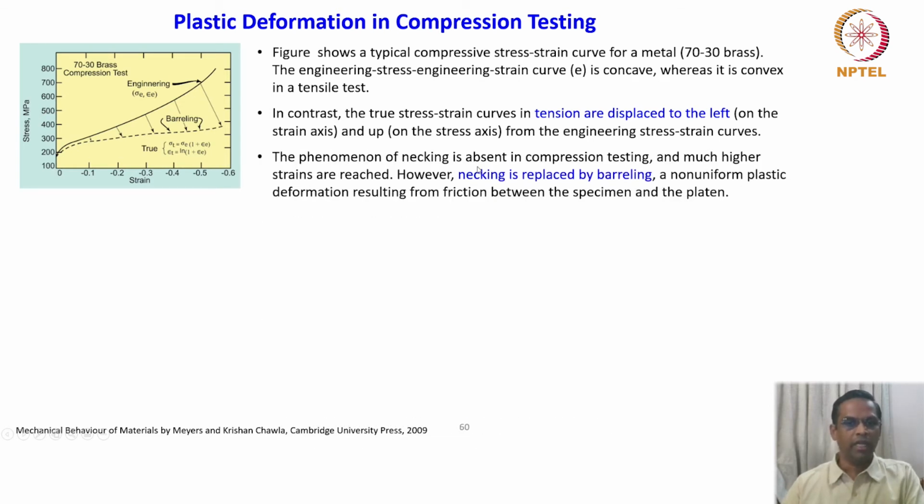The phenomenon of necking is absent in compression loading, and much higher strains are reached. Okay, there is no necking in this test. However, necking is replaced by barreling, a non-uniform plastic deformation resulting from friction between the specimen and the plate end. So what is this? This region is marked as barreling, which is very, very important.